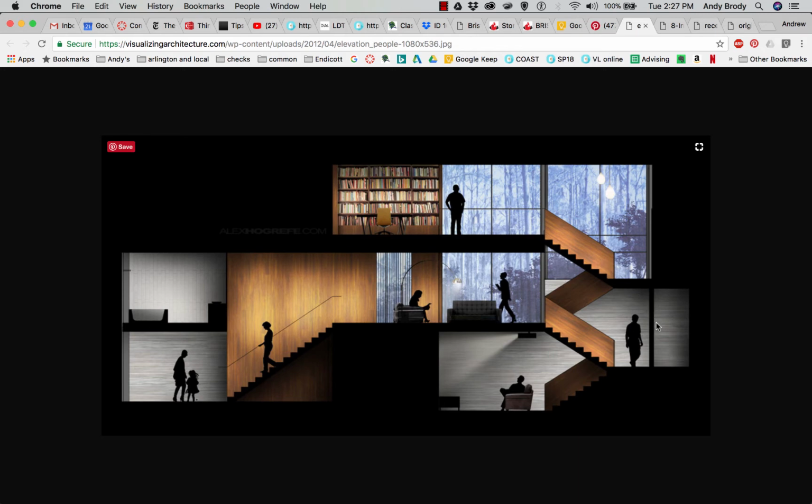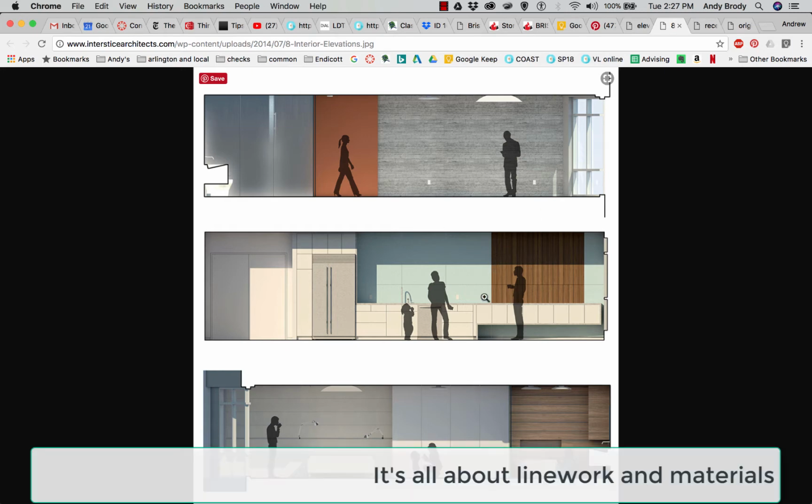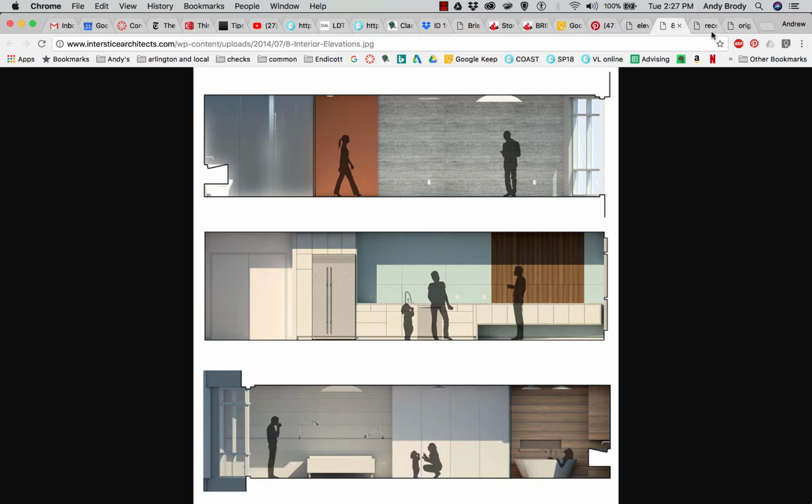The biggest thing is to represent your interiors. You're going to need to show materials, but also lighting, and of course architectural volume and architectural graphic standards. So for example, stairs need to be represented accurately, and you need to use different line weights and scale figures. Here, a slightly different style, more focus on the daylighting, but also scale figures, materials, and in this case, a standard shadowing pattern, as if the building were cut away.